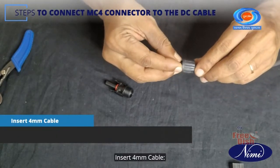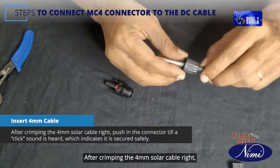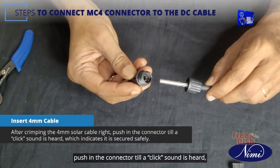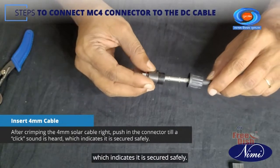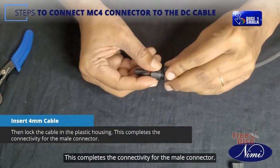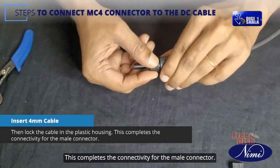Insert 4 mm cable. After crimping the 4 mm solar cable right, push in the connector till a click sound is heard, which indicates it is secured safely. Then lock the cable in the plastic housing. This completes the connectivity for the male connector.